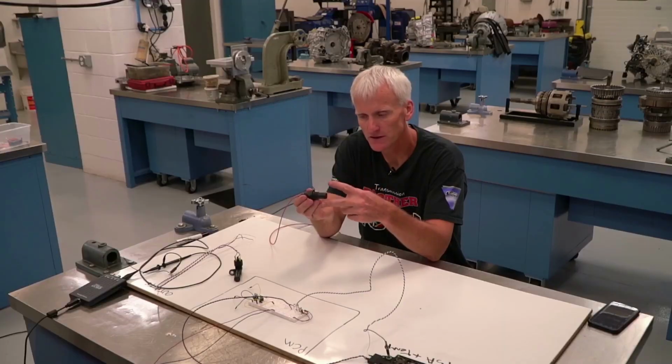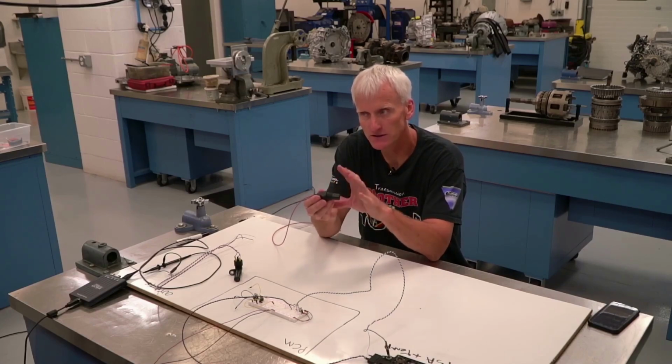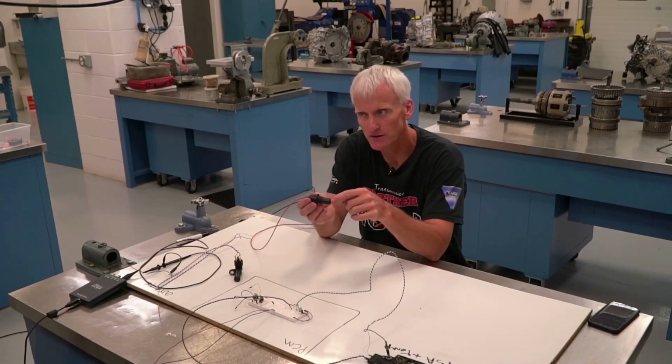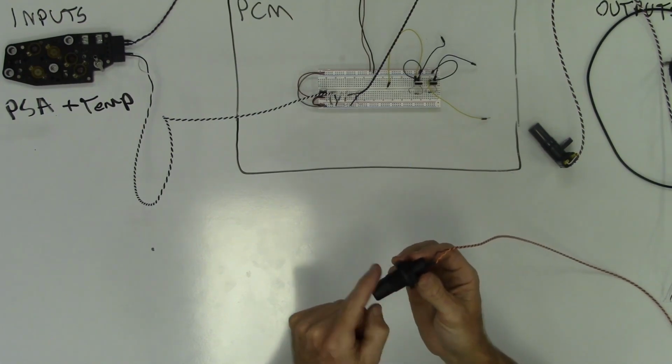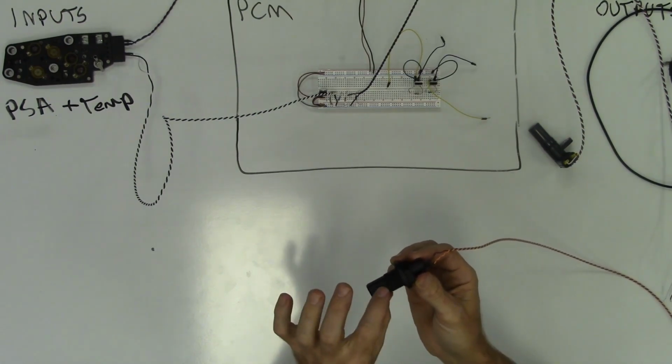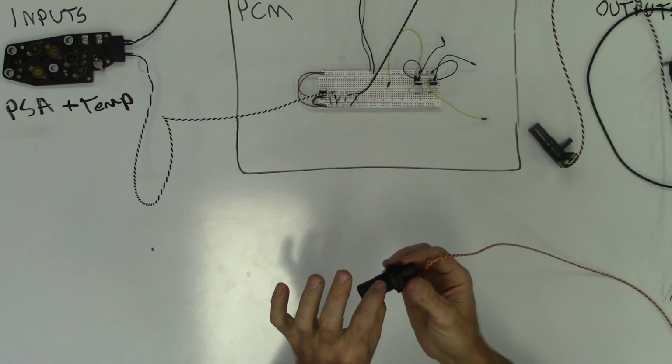When the tone wheel rotates and there's a gap between the permanent magnet, the flux lines can grow back out. When the tooth lines up, the flux lines collapse; in between, they grow out, so you get this constant in and out, in and out, in and out action going on with these flux lines. Every time a flux line collapses and expands, it cuts across the conductors inside, the coil of wire wrapped around it, and induces AC voltage.